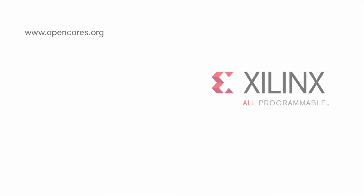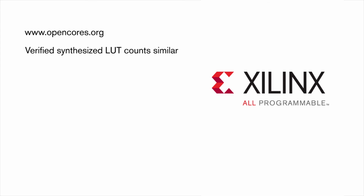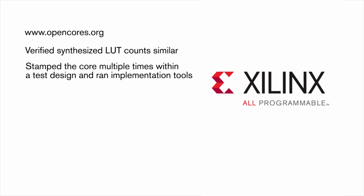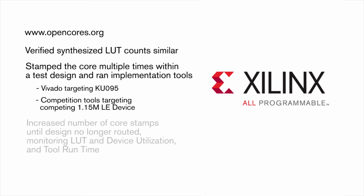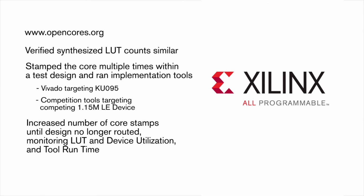To put the architecture and tools to the test, we downloaded a low-complexity design core from opencores.org. We synthesized its RTL with Vivado and the competitor's tool to verify that both tools produced about the same number of LUTs for the design. Then we stamped the core multiple times into a test design, running through Vivado and the competing implementation tools, targeting a 1.15 million logic cell device, while iteratively adding more stamps to the test design until each tool failed to route. Along the way, we monitored device utilization, actual LUT count, and tool runtime.